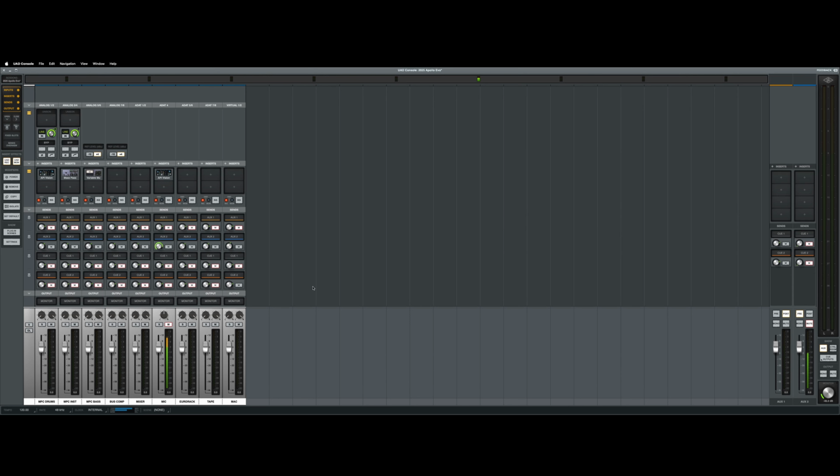I've got the Apollo working as the master and the Evo working as a slave at the minute, but they're working together as one interface, so I can take advantage of all analog and digital inputs and outputs. If you don't have an ADAT input on your other audio interface, you can just do them as USBs. So if you've got spare audio interfaces, instead of thinking, I'm going to buy a whole new interface because I just want 2 more inputs, think about the aggregate device.